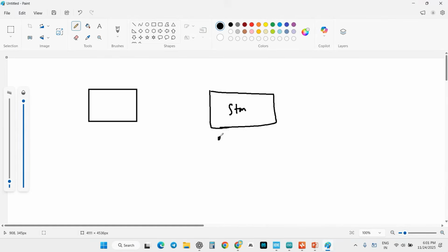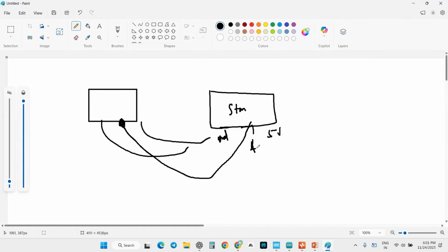One end of the potentiometer is connected to ground and the other to 5 volts. Based on this, the analog data on another analog pin changes. It is considered an analog voltage, and that analog voltage is converted to digital form with the help of the ADC converter. That's what that project is.